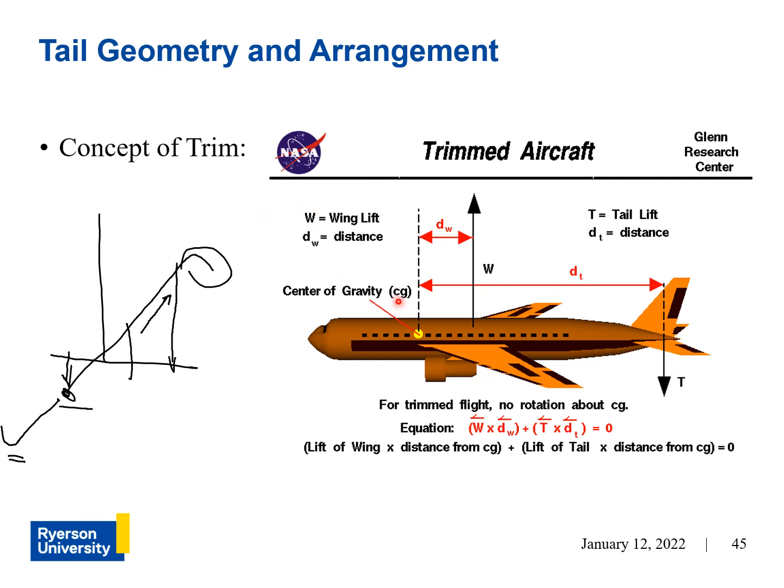Likewise, the vertical tail surface fulfills the same role essentially, but in the yaw direction instead of the pitch direction. Although most aircraft are symmetrical, thus in normal flight, unbalanced aerodynamic yawing moments aren't really as prominent as this pitching moment here. But it's still there for stability purposes and countering moments in the case that there is a moment in the yaw direction.